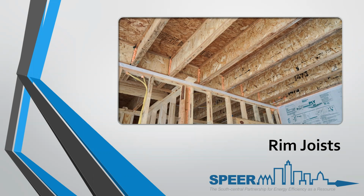So creating that, you must separate that. All openings must be blocked. All gaps must be sealed. In this photo, you see the band joist over the garage wall, isolating the floor from the garage and the conditioned space. So on the right, on that floor, it will be insulated. On the left, it will not, because it's between two conditioned spaces. So you're going to separate it with blocking.